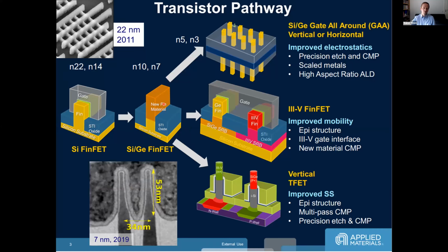And this slide is not from me. It's from a well-known semiconductor company, Applied Materials, where they project the possible paths for next generation semiconductor structures, in this case here for transistors, as we already several years ago went from a planar geometry to these three-dimensional structures that we have nowadays in computers with these FinFET geometries, which are still at the limit of getting scaled further down, also due to heat losses.